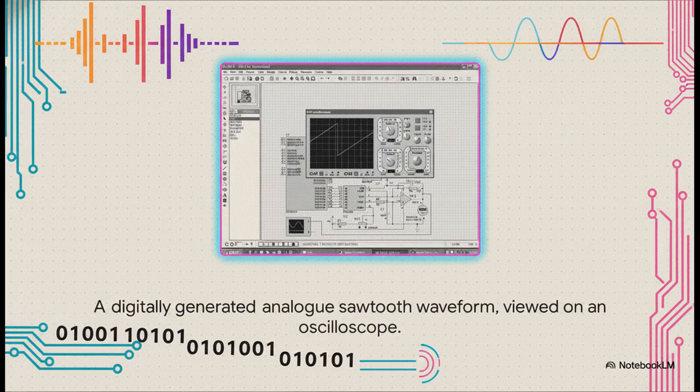And here is the payoff. What you're looking at on this oscilloscope is a perfect analog sawtooth wave. But here's the cool part. This smooth, rising voltage wasn't created by a traditional analog circuit. It was generated entirely by a digital process. The microcontroller is just running a simple loop, sending a number to the DAC that counts up over and over again. This kind of precise, digitally controlled signal is essential for all sorts of things, like generating audio tones or controlling laser scanners.